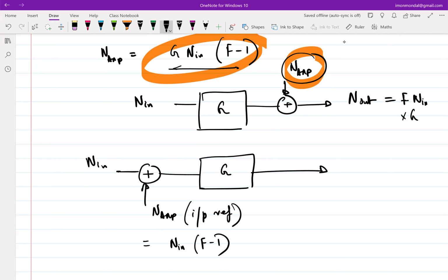Okay. So once you understand the first picture, everything is deduced from there. But the reason we are going through this is because, firstly, all data sheets of all RF components are measured with respect to noise figure, right? Nobody will give you exact noise in terms of dBm per hertz. It will be with respect to noise figure, and there's good reason for that. The main reason is it is always assumed that your input is a 50 ohm load that comes from the antenna, and everything is matched to 50 ohm, which means the input noise is fixed at 4 kTr times 50.